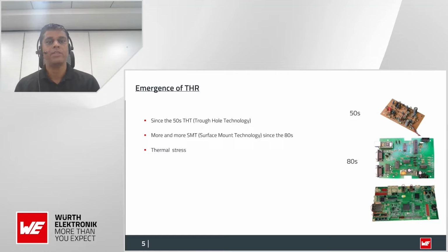So what happens here is that on the PCBs you have very small components like capacitors and chip beads, ferrites, which have to go through a lot of thermal stress. That means when you are assembling by reflow, it has to go to 265 to 285 degrees. Again, when you are doing the wave soldering process, that product has to go through high temperature again, like 235 degrees.